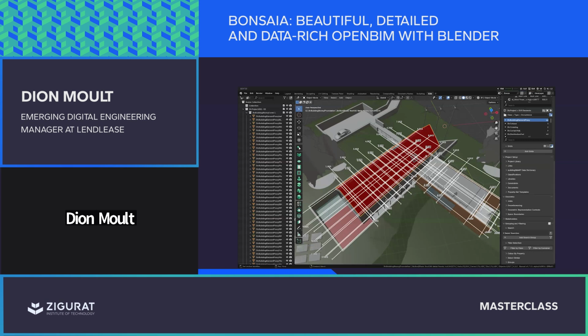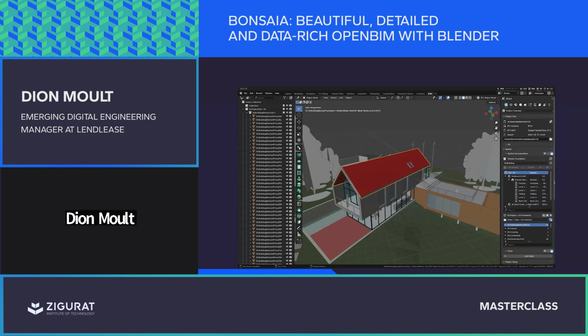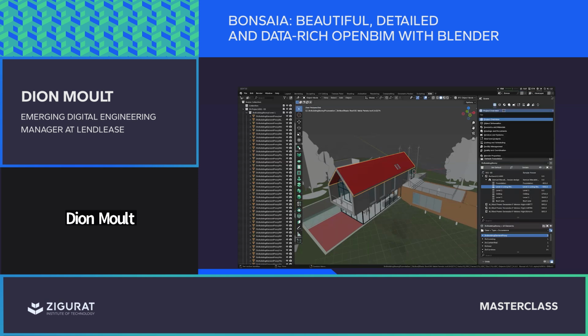These grids are in the way, so I'll just turn that off. What you'll notice immediately is that this is far more sophisticated than an average IFC viewer. This shows you things to a great level of detail, right down to how IFC actually works under the hood. So you can see details you may not see in other software, for example this spatial breakdown. I can have a site, a building, many levels, and within them all of the objects within those levels. And I can also go into a number of other tabs here.